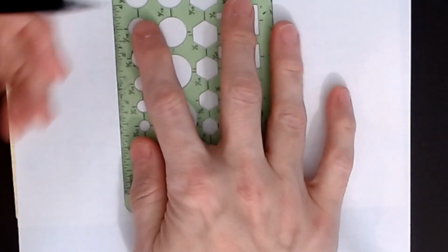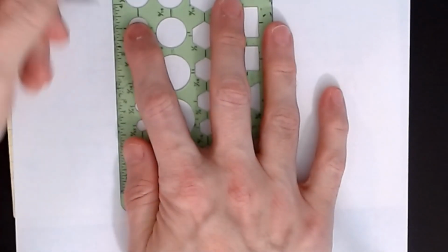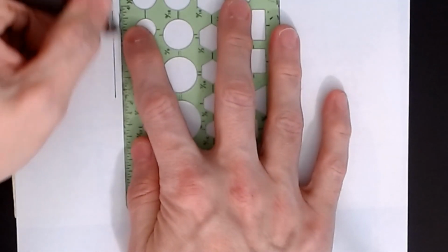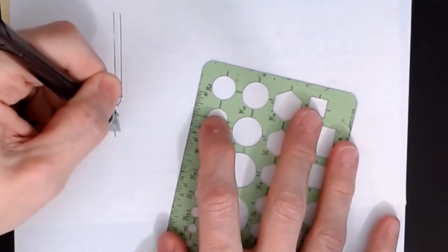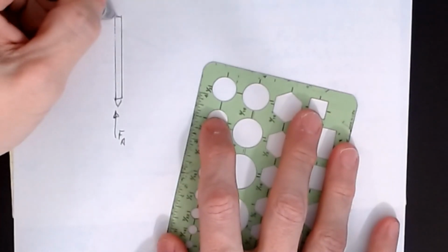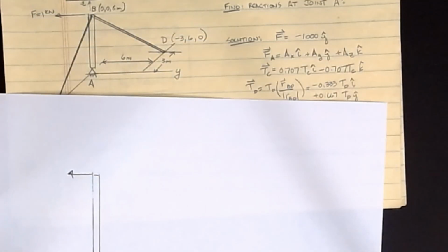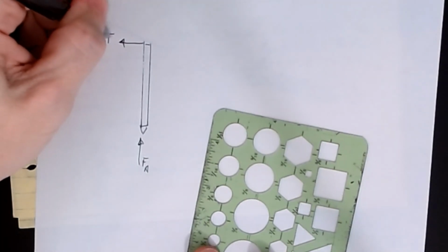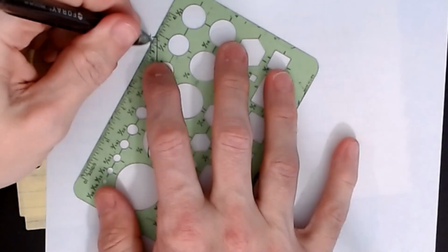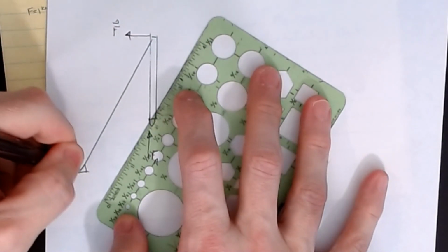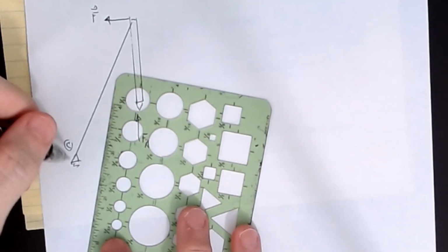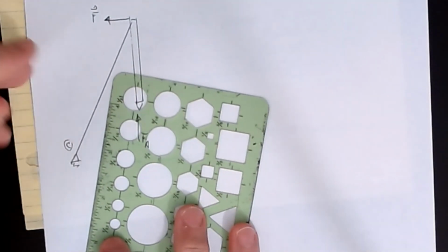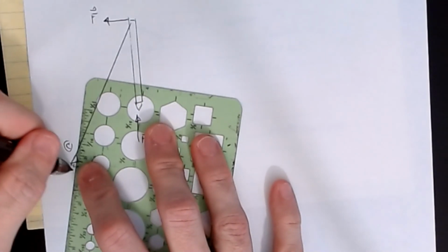Get my straight edge here. Sorry about that. Okay, the first picture that we should always draw is the one of the uncut system. Now, again, I've skipped that step because what you have is a force vector at A. I have what we were calling my F vector happening here, and then you had cables coming down to a pin support at C. Now, cables, their connection is always considered a ball and socket. There is no moment. You can't bend a rope. It's only tension allowed.